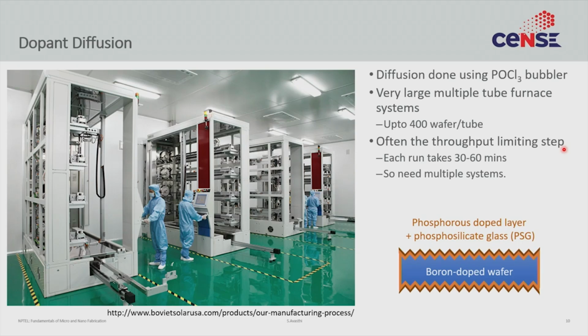In this case, the increase in cost is only in a furnace, which as things go is not a very expensive equipment, so it's okay. But if you were to do the same thing, say for an implanter, which is a way more expensive tool, that would become financially untenable. So that is the reason why diffusion won out over a more accurate or more repeatable implantation.